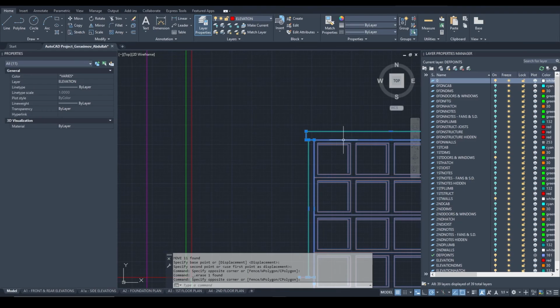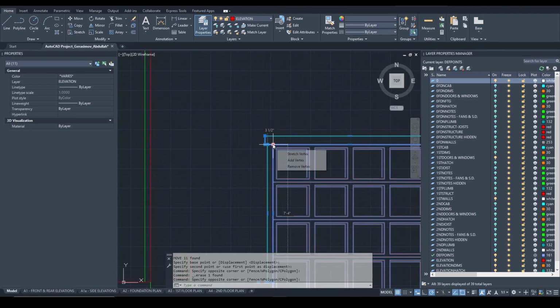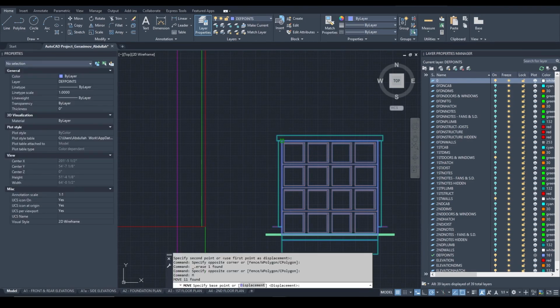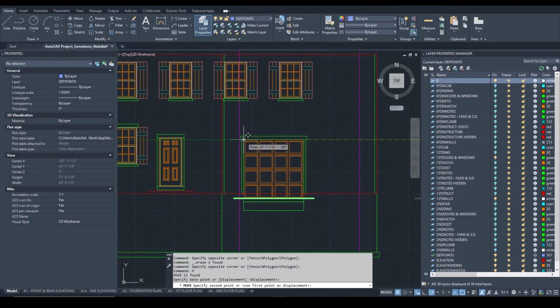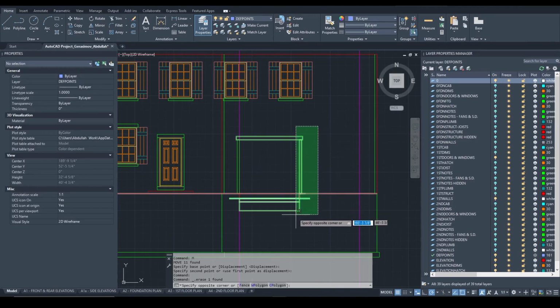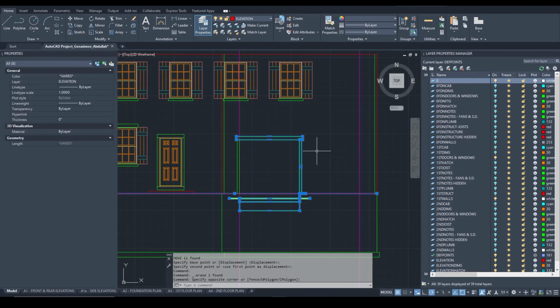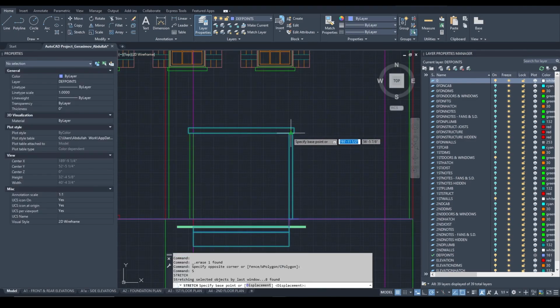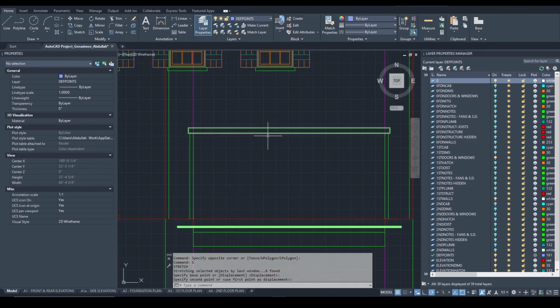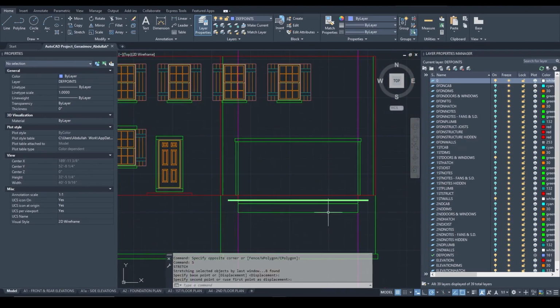You can go ahead and copy it from the top left corner of the garage door itself, or move it in this case. We can now remove the actual door because we're not going to have this door. Select the right side of the entire assembly. Make sure that you highlight it in green and drag it from the right side of the future garage door to the right side of the magenta line.